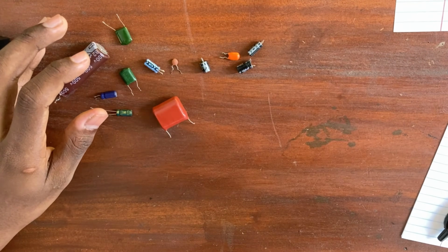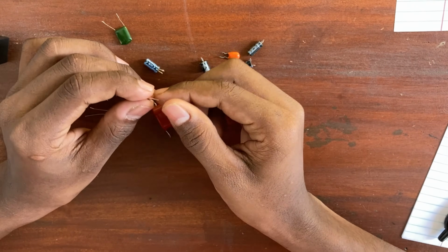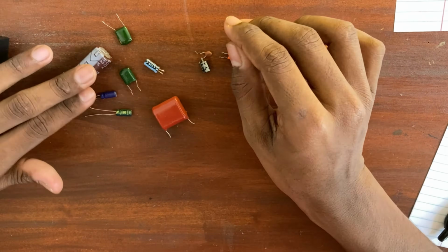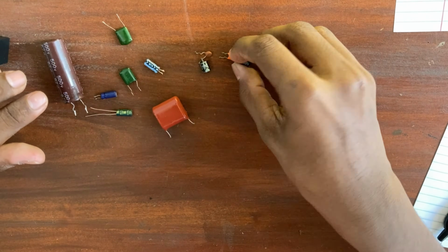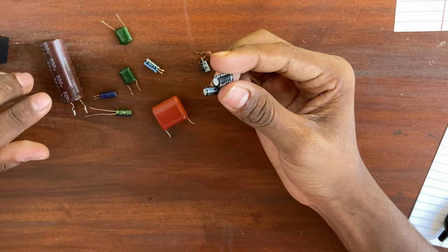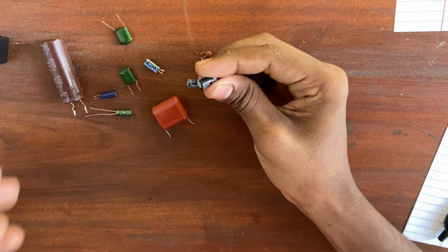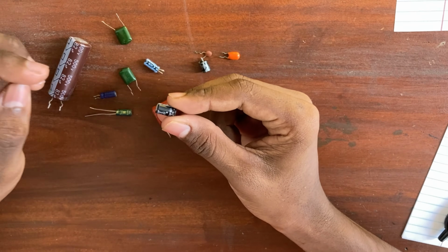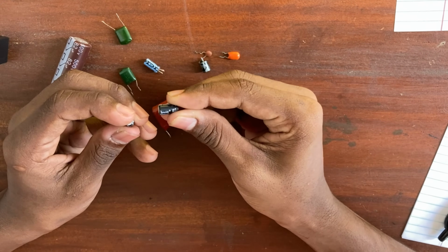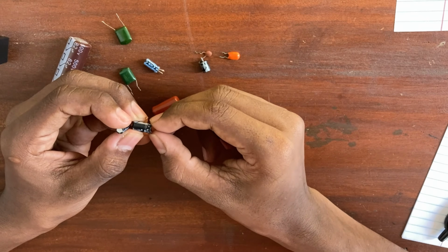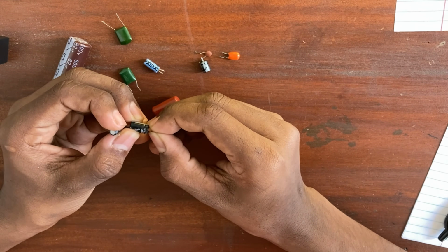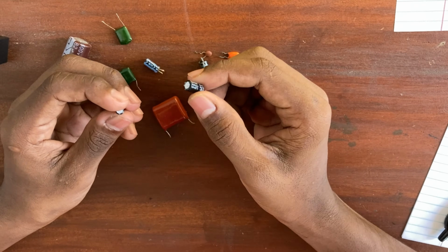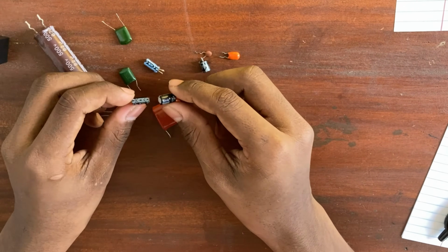There is a two-layer type of these capacitors which are less dependent on the temperature, but electrolytic capacitors change the capacitance value depending on the temperature. I mean, it's not very accurate to use them in a high temperature environment or near components that get very hot. So you should really consider that.